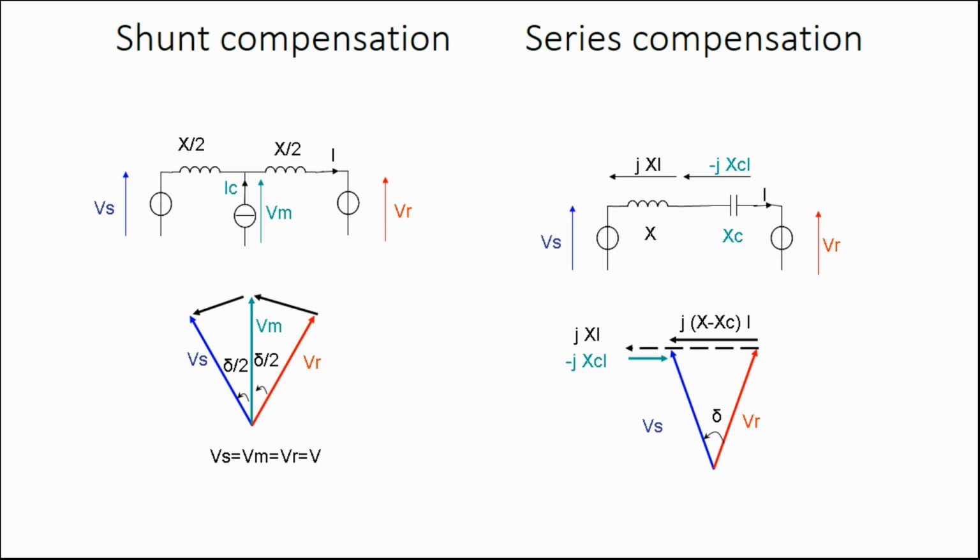A flexible alternating current transmission system, FACTS, is a system composed of static equipment used for the AC transmission of electrical energy. It is meant to enhance controllability and increase power transfer capability of the network. It is generally a power electronics-based system. FACTS is defined by the IEEE as a power electronic-based system and other static equipment that provide control of one or more AC transmission system parameters to enhance controllability and increase power transfer capability.